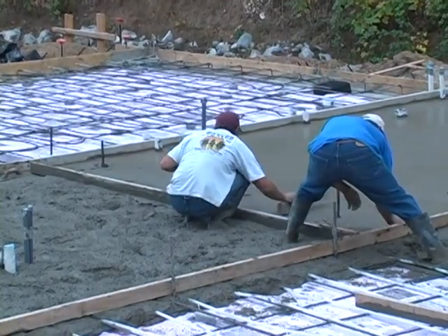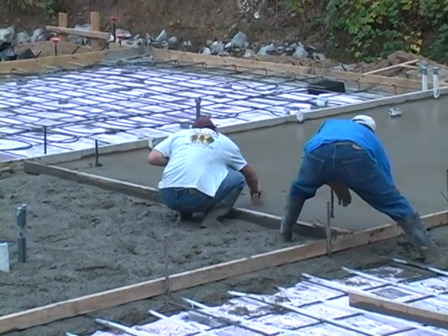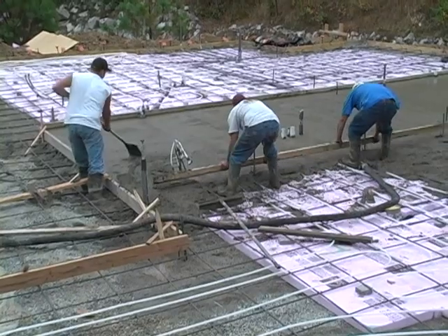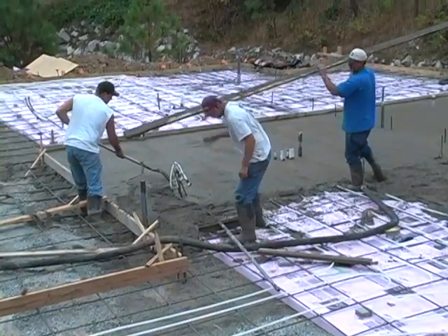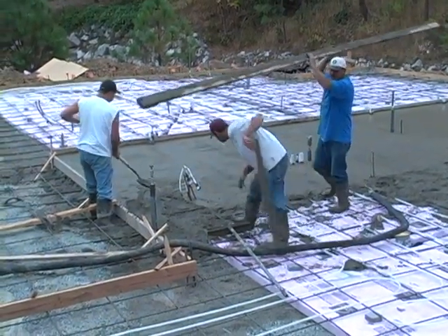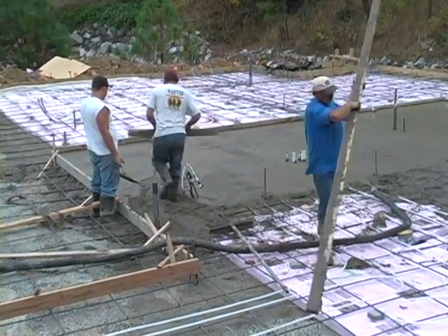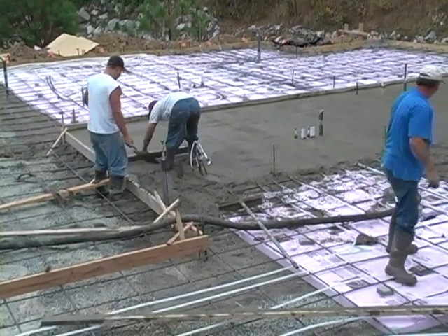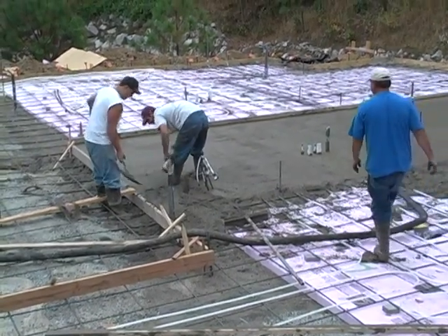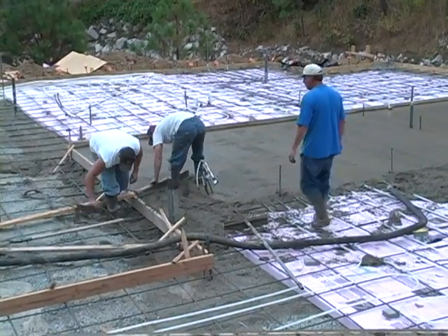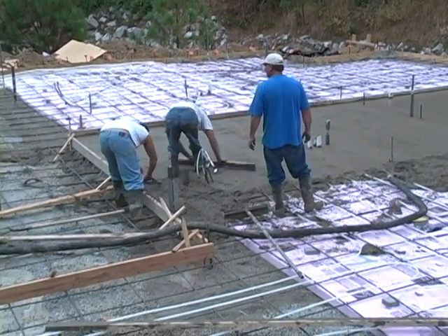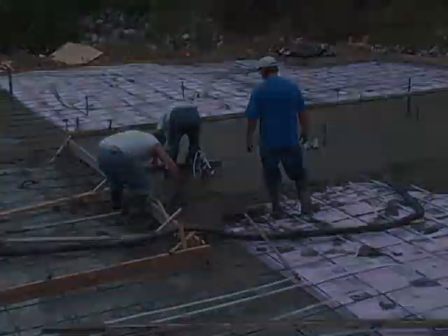And you can also use a smaller section of 2x4 to just level out some places that you don't need to run the entire screed board over. And when you're ready, when you've got your section in place, you can pull out your temporary screed board and just set it to the side. This is where these screed posts come in really handy to do a multiple stage pour like this. So with that set to the side, we can level out areas where we have a little bit of imperfection, and then come back and use that surface now as the screed for that side of the pour.